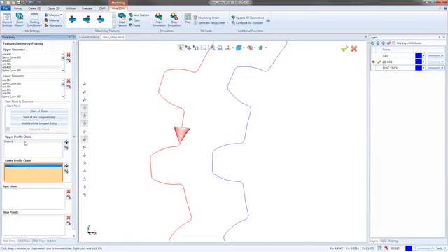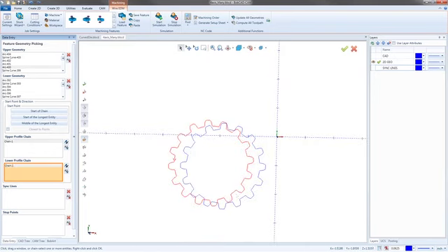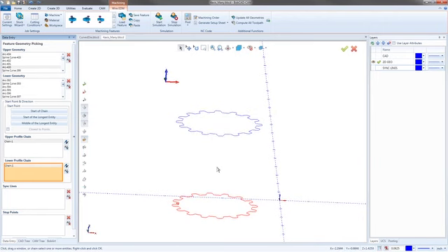Otherwise, if you put two start points on opposite sides of the part, it will put those start points on the opposite side of the part. I actually just did a part a few weeks ago with a guy that, in the middle of the part, was basically two funnels, one on top of the other, and he had to figure out a way to cut it. The only way to cut it was to perfectly center the wire right in the middle and then set one start point on this side and another start point on this side.